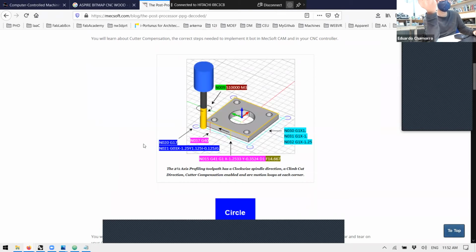So in the post processor, there are a lot of things involved. First, how the movements are created, then the tolerances embedded into the machine by the manufacturers. If it's a good manufacturer, the machine has tolerances, and they can be accounted for in the post processor. So there are a lot of small details, and making a post processor in general is not simple.